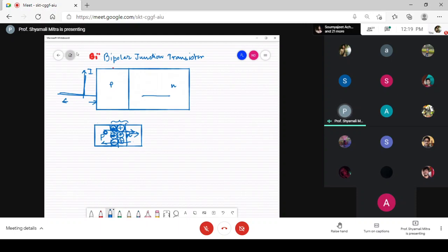This is the bulk of the semiconductor, and this is the edge of the depletion region width or the space charge region width. Why is it named the space charge width? We have also discussed this earlier. I think you know that these are actually covered with the space charges, or the immobile ions or immobile charges sitting over there. This is called the space charge region also.